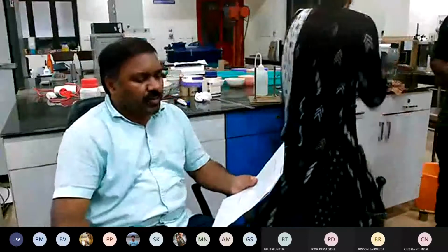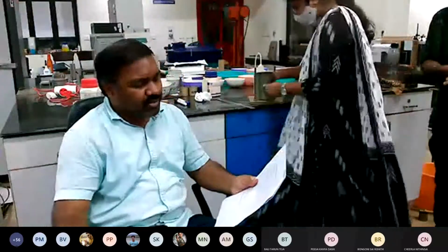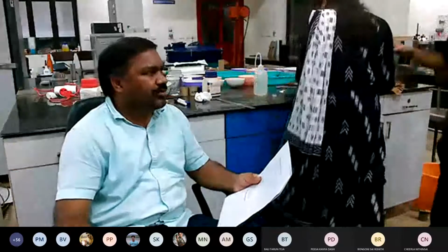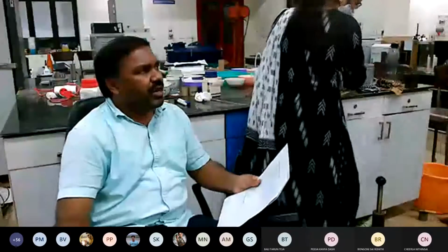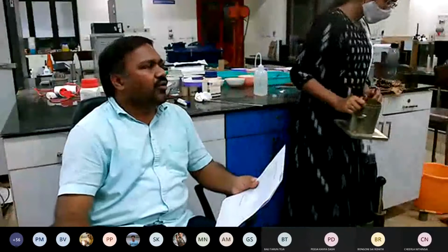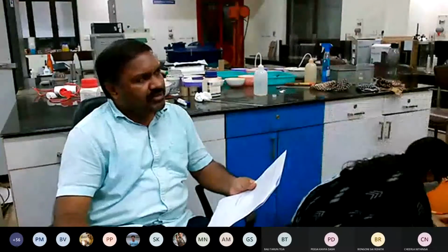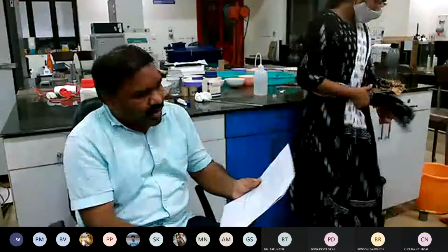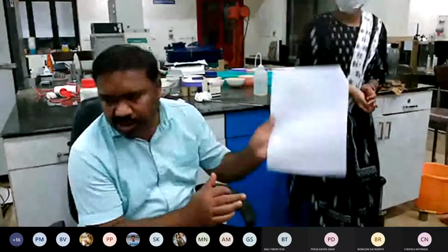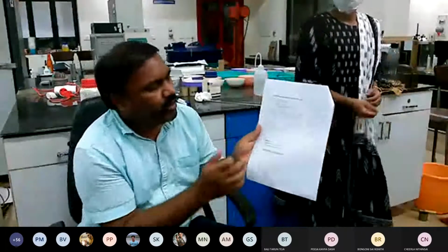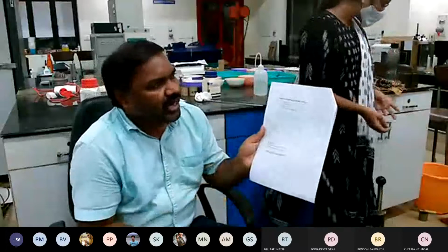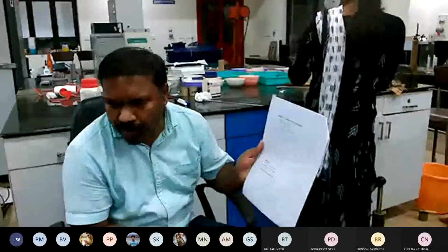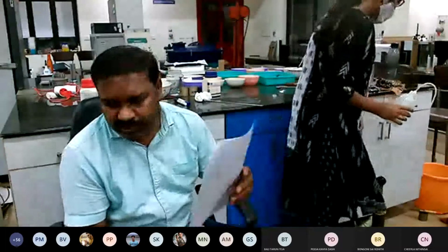Okay. So please fill up your handouts. Diameter of the mold is 99.46 millimeter. Height is 127 millimeter. And weight of the mold plus base plate is 4.623 kg. Now you need to start filling up this table. So against serial number 1, you can start with a moisture content of approximately 2% or 4%, whatever.